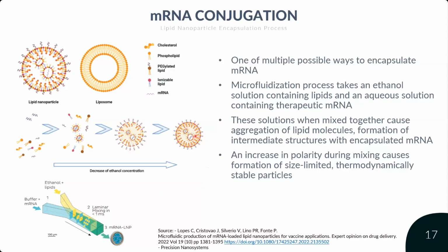Yeah, and then if you could talk a little bit about the stability issues that people need to be aware of as well, and critical process parameters, and how are they going to impact the process? Certainly, and I think the thing to really consider is that we want consistent sizes so you can deliver therapeutic mRNA payloads that are consistent from vial to vial, lot to lot, and the way to control that is via flow rate, proper mixing, and microfluidic channel design.